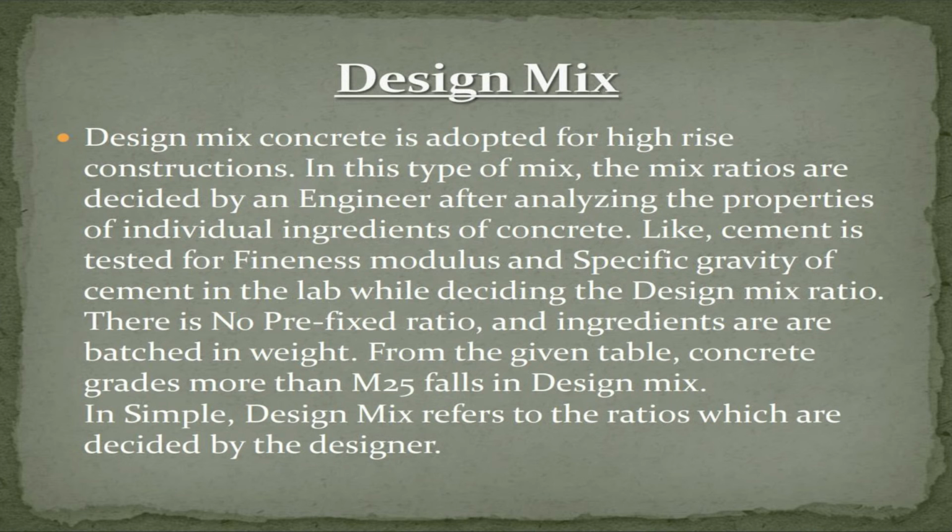Design mix. Design mix concrete is adopted for high-rise constructions. In this type of mix, the mix ratios are decided by an engineer after analyzing the properties of the individual ingredients of concrete. For example, cement is tested for fineness modulus and specific gravity in the lab.